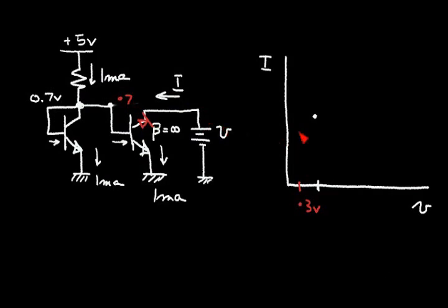And as I increase voltage and I plot the current, this current's going to have some slope due to the characteristics of this NPN transistor. So it's not an ideal current source. It has an advantage that I can go down to perhaps 0.3 volts or so, have to avoid this region of operation. But not too bad of a current source, and it's very useful in many different applications.